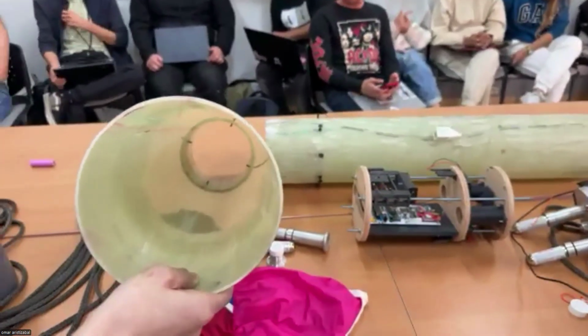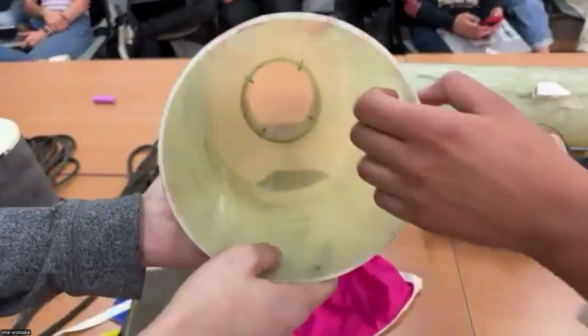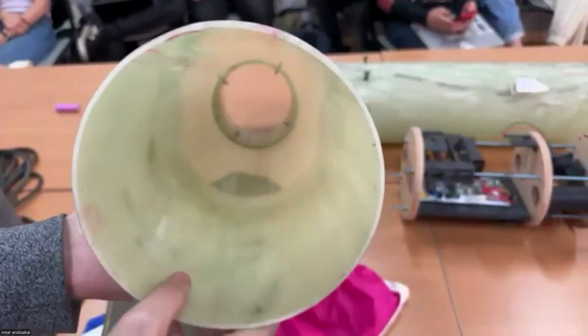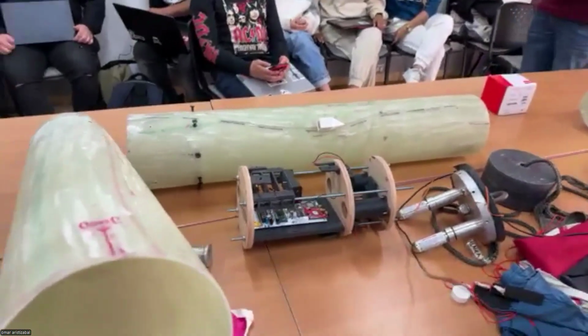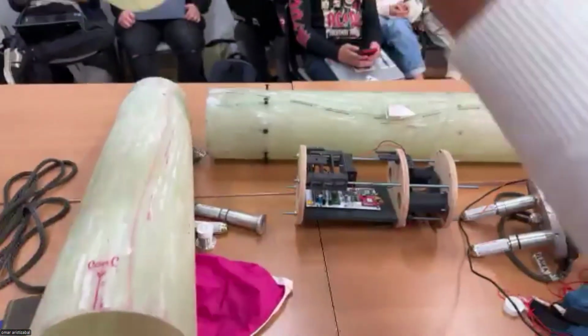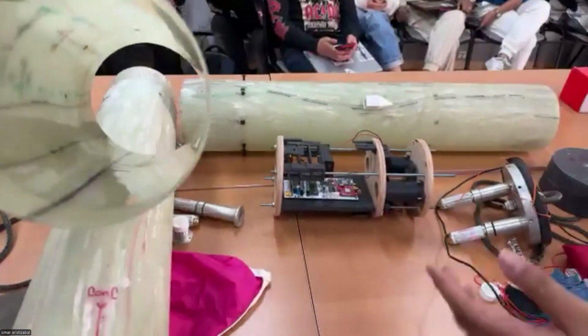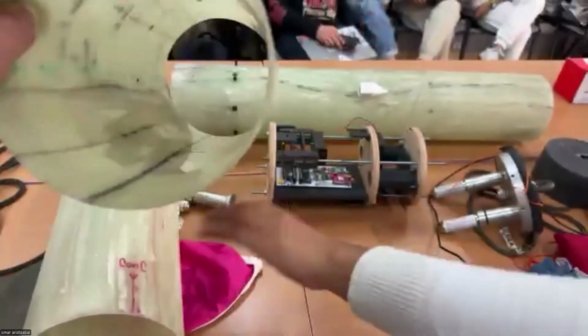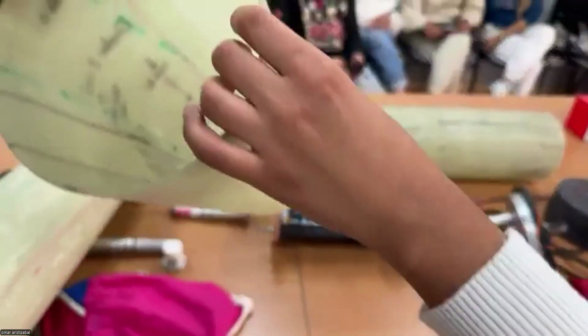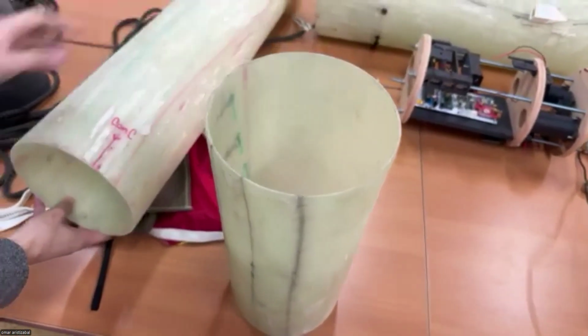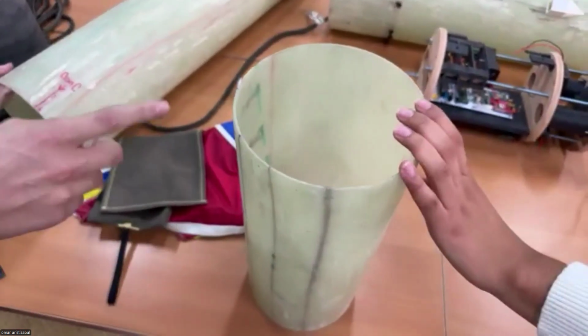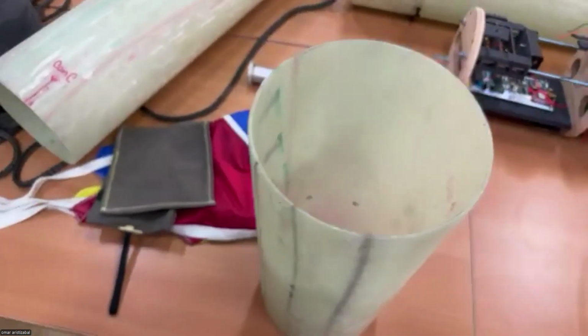That will be the thickness of the body tubes. The team did a really great job analyzing all the forces that the rocket will endure. Also, we did material tests of the fiberglass they're made from, in order to verify the material properties and to calculate an adequate thickness. We have a safety factor of 3.